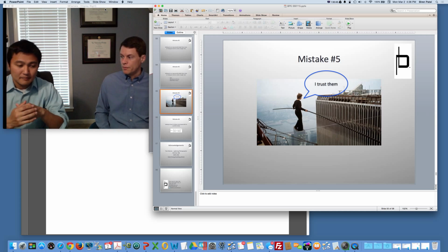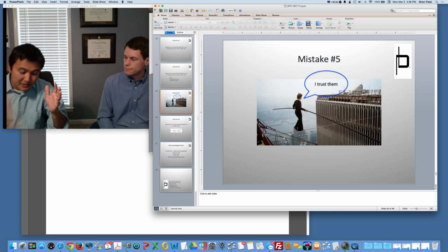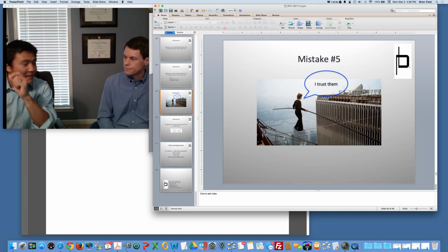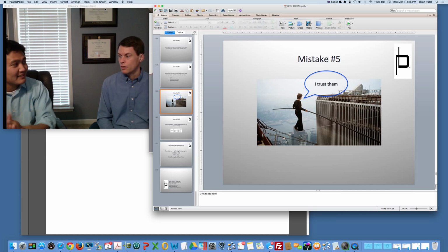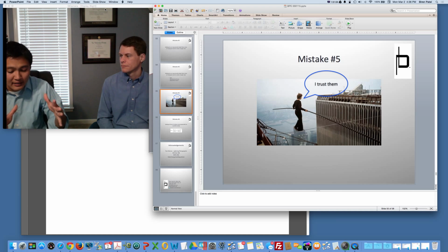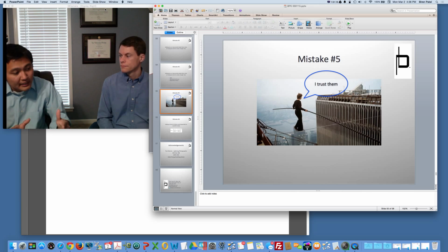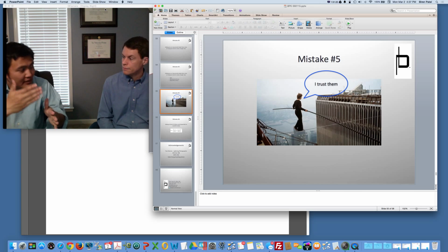I guess a mast is stronger and less likely to fail in the event of a tornado or something like that. The mast itself could fall down, but certainly the wire snapping off and falling is far more likely. And I'll say this: we have a lot of clients in hurricane areas, like Florida, because obviously there's a lot of lightning in Florida, and some of our clients will say no shield wires at all. Some of our other clients will say shield wires are okay, just make sure they don't cross bus. That way, if they fall, hopefully they'll fall straight down.